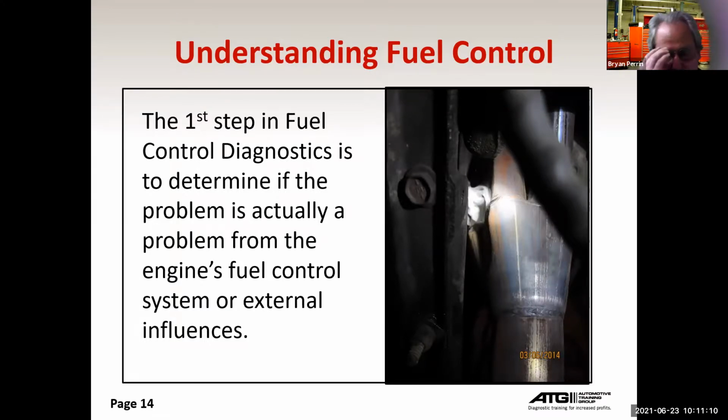So with welding, you're flowing the metal that you are attaching, not just the rod, but also the metal you're attaching to. You're turning that metal into liquid. With soldering, you're not doing that. You're turning the solder into liquid, and it is adhered to a metal that is not being turned to a liquid. So that's the big, overly simplified difference between a solder or a braze and a weld. Okay.